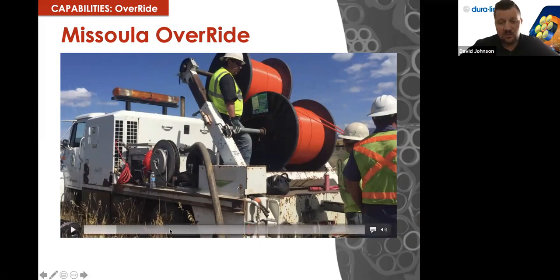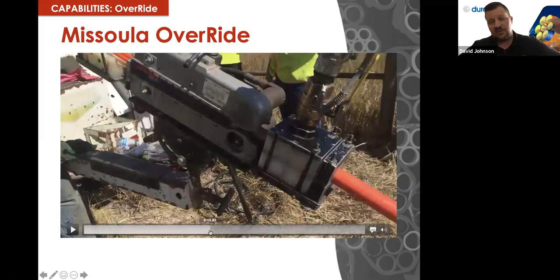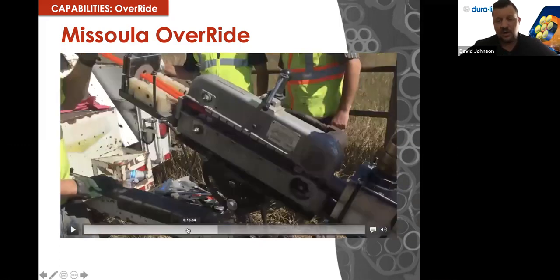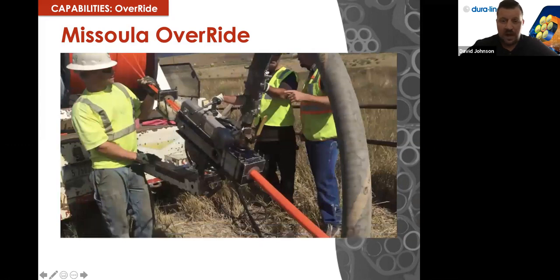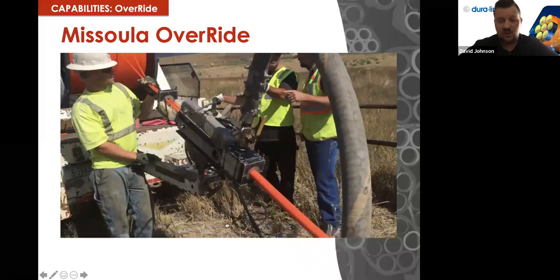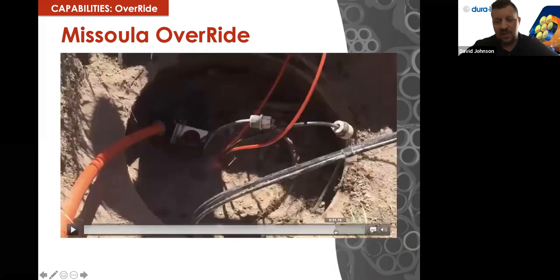As it's going through the machine here, those tracks are pushing it. You've got your air pressure machine right there. So this is where air is going into the existing conduit and pushing air forward through the existing pathway, that 2-inch conduit. And then as you saw, as it goes down into the handhole here, we've got that Y block.